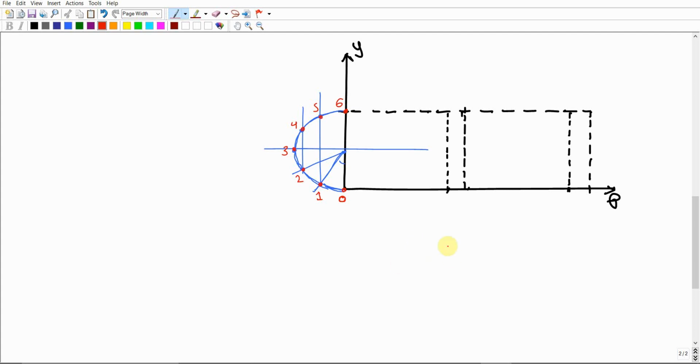Then your objective is to break down the theta axis for the simple harmonic motion for the rise period into 6 divisions, as we did for the 6 sectors. For this semicircle, we also have to divide into 6 divisions over this one. But remember, how much is the length of this period? It is 5 centimeters. So your objective is just to divide 5 centimeters by 6. This gives us exactly 0.833 and lots of 3's.